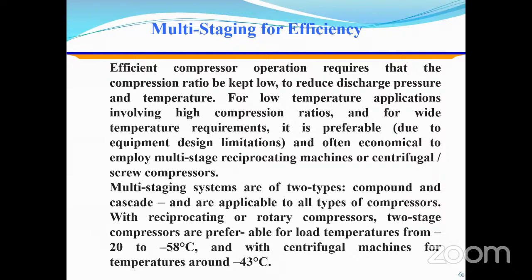Suppose the chiller package capacity is 200 tonnage, then 2 compressors of 100 TR can be installed. So if the load is reduced, then it automatically switches over to lesser capacity. So one compressor is switched off. So that is called the multi-staging of the compressors. Take care of the loading pattern.